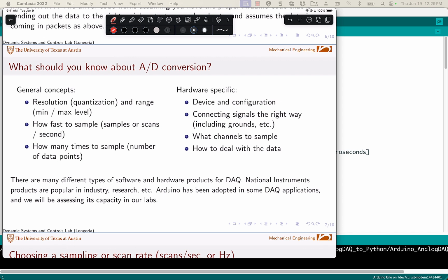Be mindful of that. So, for example, if you had a DAQ device that had 16 bits, that means you have 2 to the 16th levels at which you can resolve voltage, right? If you have a 4-bit converter, then it's a very crude resolution of a voltage value. So be mindful of resolution. This is what you pay money for.